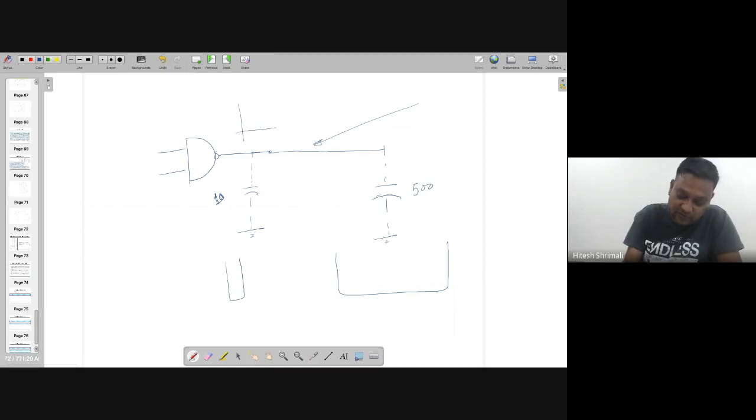without connection, you might see something like this, 1 and 0. After connection, you might see something like this. So which was the need of the driver circuit, or it does not have enough logical effort. So in that case, you need to fix that. If you need to fix it, the best way is just to add an even number of stages of inverters.